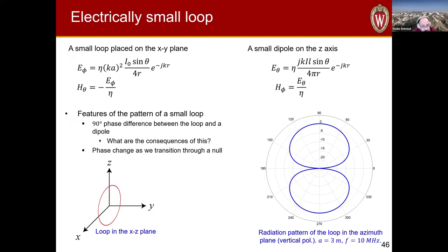So there is also another type of antenna that we can use. It's an electrically small loop antenna. This is also used conventionally at HF frequencies as well. And if you have a small loop antenna placed on the XY plane, the radiation from this loop antenna would be the dual of the radiation from the Hertzian dipole antenna. So you'll get basically the same donut-shaped radiation pattern. Your polarization would be orthogonal to this, and so it's a very similar type of antenna.